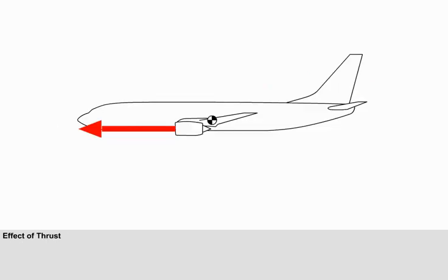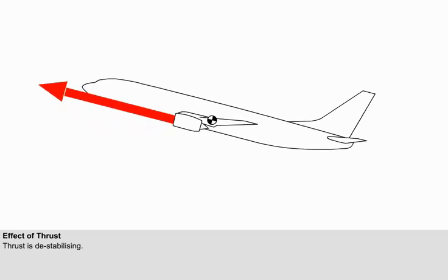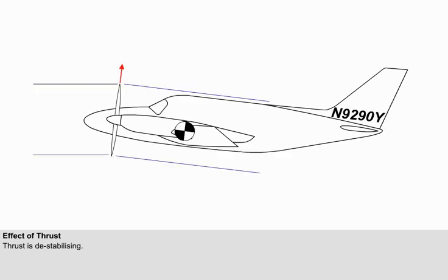The effect of thrust on longitudinal static stability will be greatest at low indicated airspeed and high thrust, such as during takeoff and the approach to landing. The vertical location of the thrust line defines one of the contributions. The illustration shows an aircraft with pod-mounted engines beneath the wing. Because the thrust line is below the aircraft CG, an increase in thrust will produce a nose-up pitching moment, which is destabilizing. A propeller located forward of the CG will also contribute a destabilizing effect.